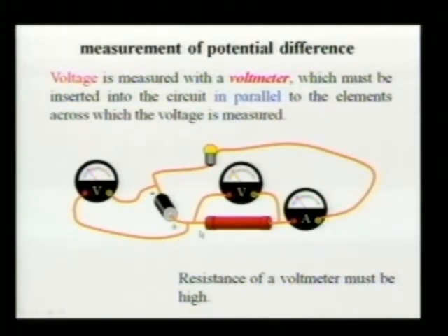So placing an ammeter parallel to the resistor will create a potential difference of 0 volts across the resistor. What current will flow in the resistor in this case? 0, right? Because in a resistor, potential and voltage are proportional. So if I connect these two points, in technical slang we will say that we shortcut that resistor, and current will stop flowing through the resistor. All the current will flow through the ammeter.